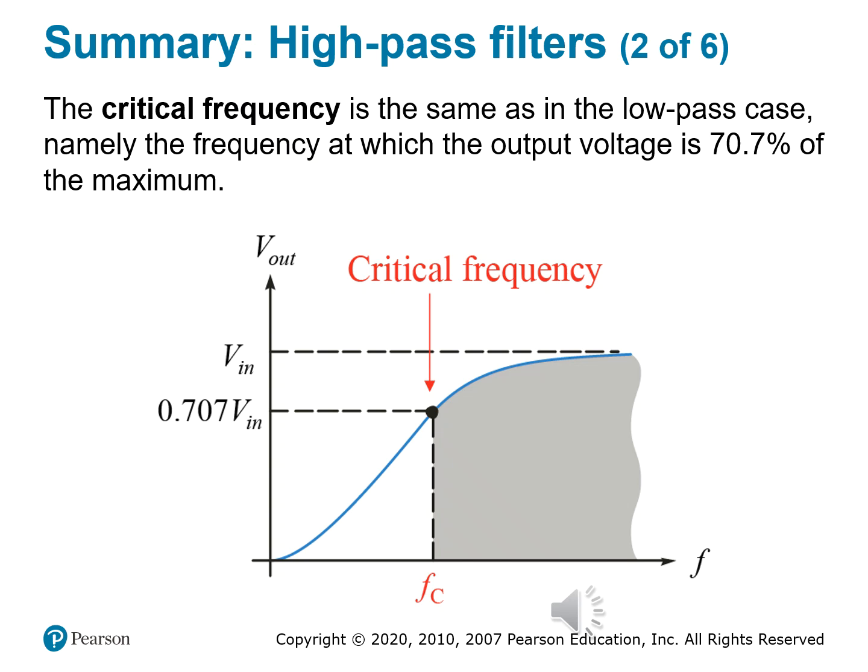So what is the critical frequency? Again, we label it as f sub c. It's the boundary line. It's the point where your filter begins to hand off more and more of the incoming signal. Technically speaking, it's the frequency at which the output voltage drops to, remember that number, 70.7% of the input voltage. And in decibel terms, remember this number, it's the negative 3 dB point.